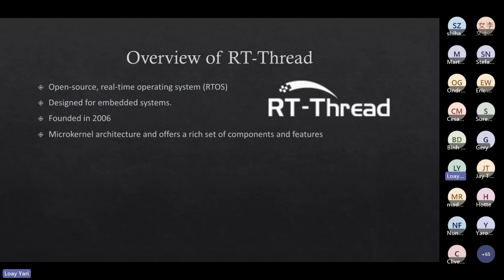So let's go to the feature basically of the RT thread. RT thread come with a range of features, including modular design. As it's modular, meaning that developer can enable or disable the components as per their need. And before that, we used the SCons environment tool, like from the command line. Basically, it's a Python script, similar like how we do the CMake or the Makefile. But now it's get more extended that we have the RT Thread Studio. So we have a package support. We can open it and install any new component shared by the community who participate in growing the RT thread.